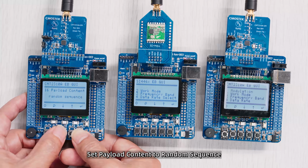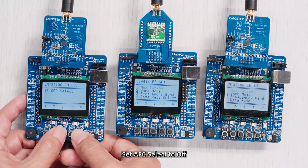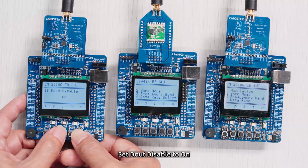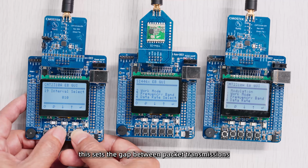Set payload content to random sequence. Set AFC select to off. Set dot disable to on. Set interval select from 000 to 55. This sets the gap between packet transmissions. Adjust based on your test needs.